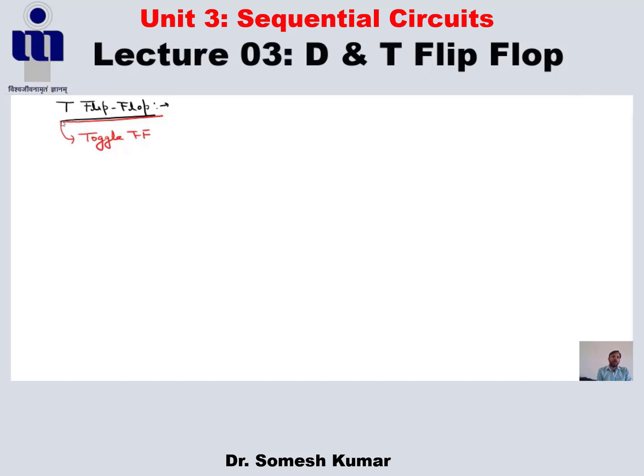So the block diagram of the T flip-flop is this. The T flip-flop is derived from the JK flip-flop. In the JK flip-flop there are three inputs, J, K and the clock, and two outputs, Q and Q bar. In the T flip-flop, I connect J to K and denote this input T. So now J is equal to T and K is also equal to T.